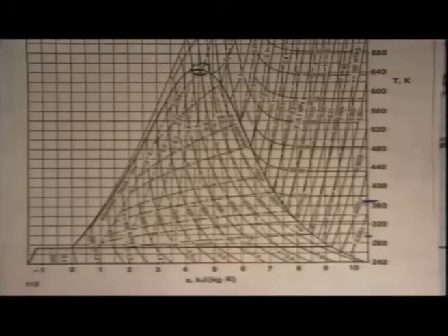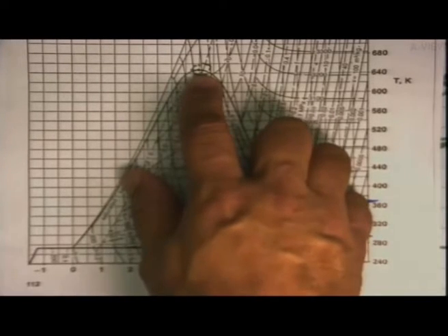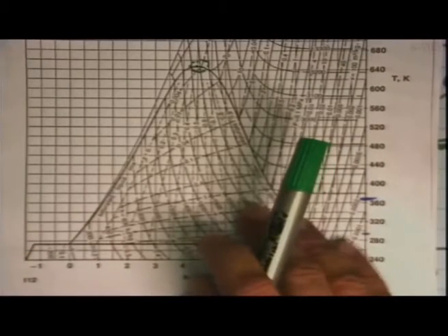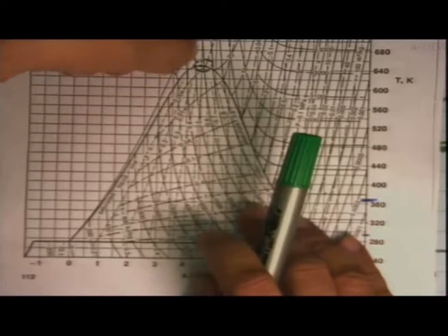Okay, so there are many practical situations where we have to worry about the critical point. Large power stations, the new ones that have come up in the country in the last 5-6 years, all have water which has been pumped to pressures above 220 bar, 280 bar, 300 bar. They will all be in lines that go beyond this.